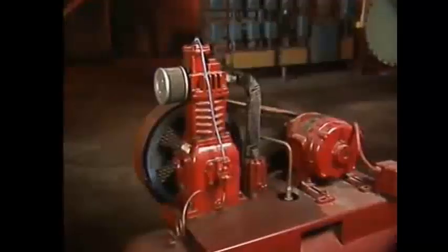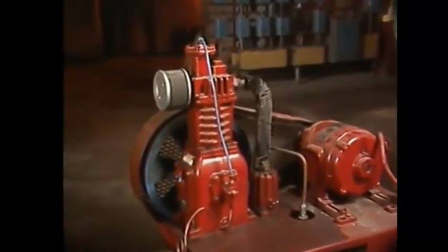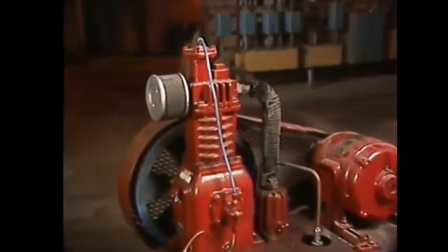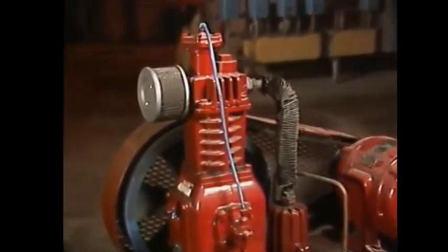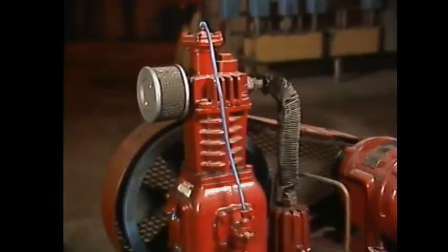Two techniques that can be used to remove excess heat from compressors and compressed gases are air cooling and water cooling. An air-cooled compressor is easily identified by metal fins on its casing. The fins provide increased surface area, allowing more of the surrounding air to come in contact with the casing and therefore keep the compressor cooler.